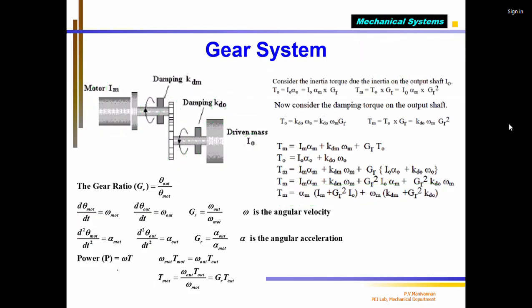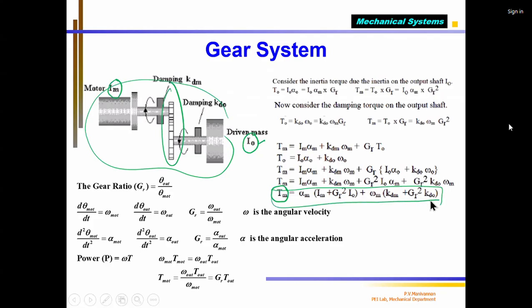As far as the exam is concerned, the whole idea is how to develop mechanical models. That's what we are seeing till now: modeling a mechatronic system, modeling a mechanical system. Motor, gear, load, all of these are mechanical. The only thing here is that I'm trying to find the motor torque to drive a particular load with this moment of inertia and this motor. What should the gear ratio be? You can find that using these equations. Any doubt in this?